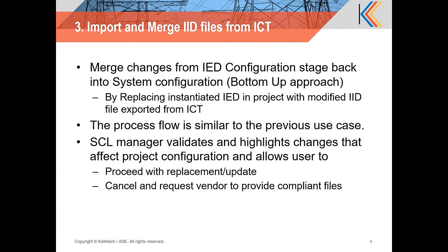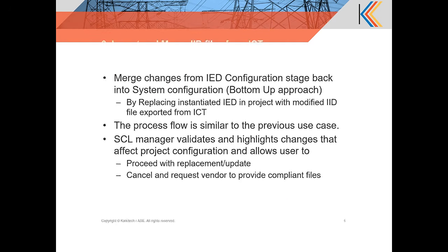Essentially, we have seen 3 use cases. First one was virtual IEDs, creating an entire bay with virtual IEDs and replacing all the virtual IEDs in the bay with real IEDs to get a replica of that with real devices. The second use case was where you have an engineered project and somebody brings a blank ICD file, which is an update because something has changed in its data model or services or something inside the ICD, and you want to update that under your configuration without removing all the configuration you did with the older version of the ICD file. And the third process is the bottom-up flow, part of your hybrid engineering solution, where you have a top-down flow and you still have changes that happen at the bottom and need to come back up into your project. So all these 3 processes have been completed.